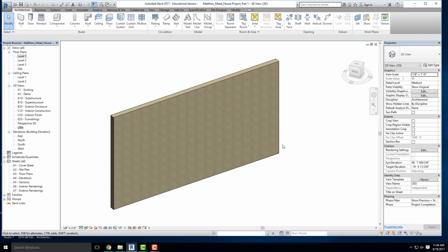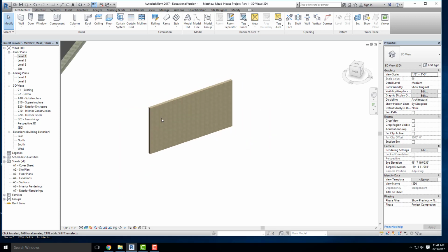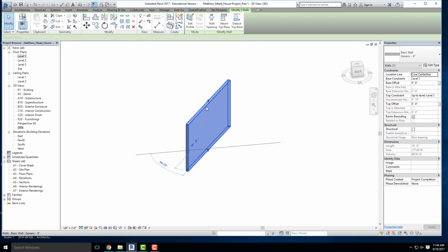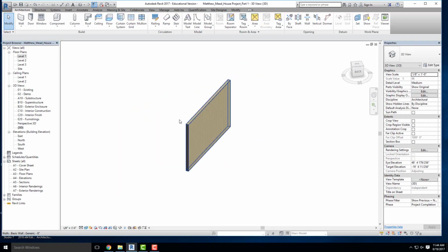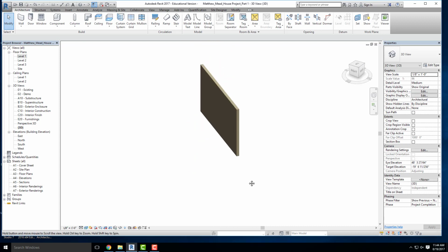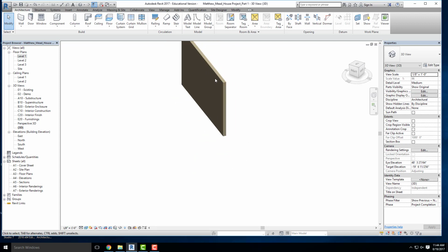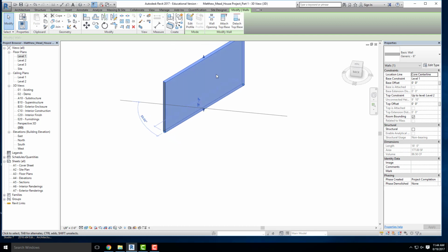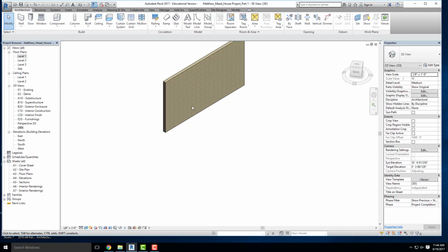Yes? If you're not gonna add it to the outer layer as a finish, for example, exterior or interior, it's gonna assume that you want the whole thing included. Exactly. So now let's change this. Let's change it to the actual correct situation. Okay, so you notice that by changing, I just added the cement plaster layer to the stud, it changes the entire wall, inside and out, which you probably wouldn't want because you don't want cement plaster on the inside of your bedroom or something like that, okay?